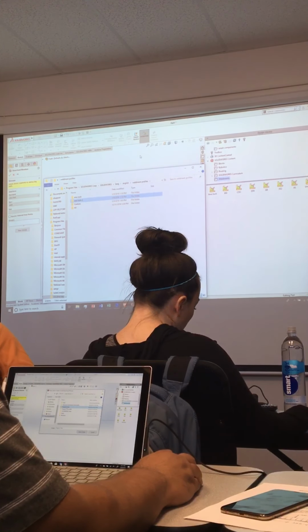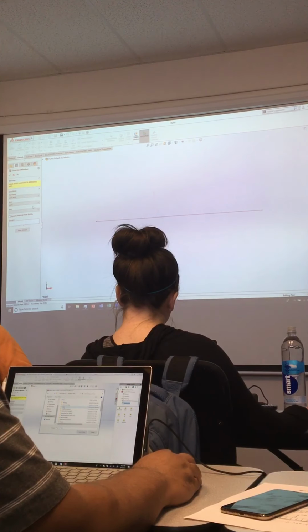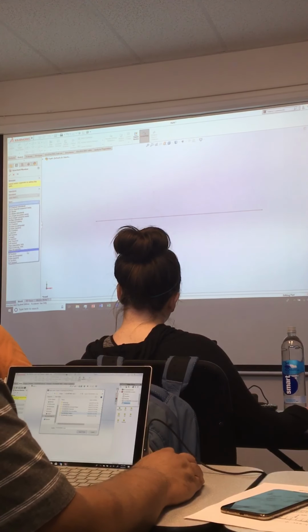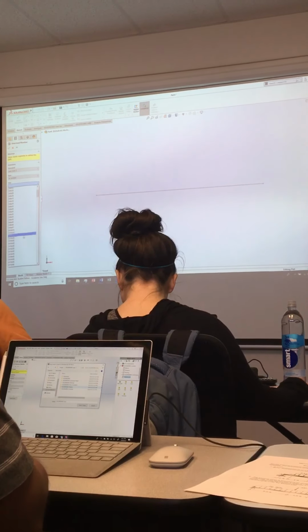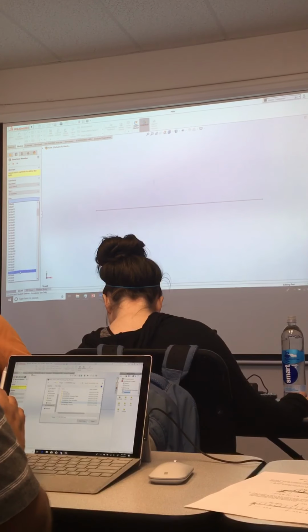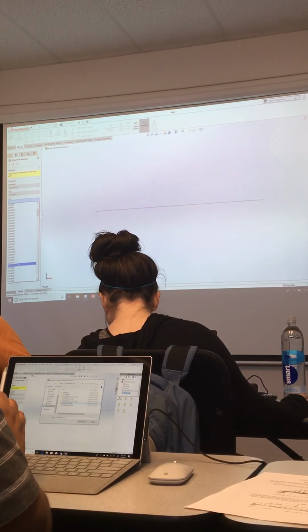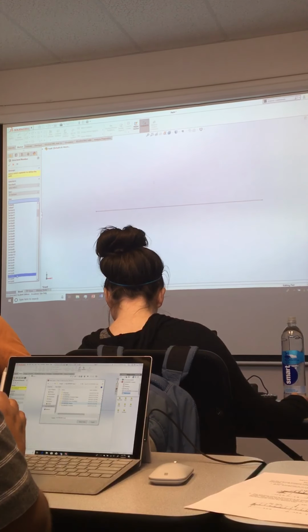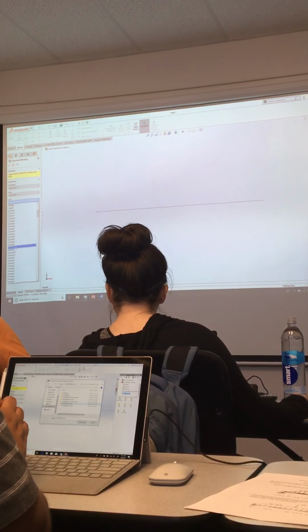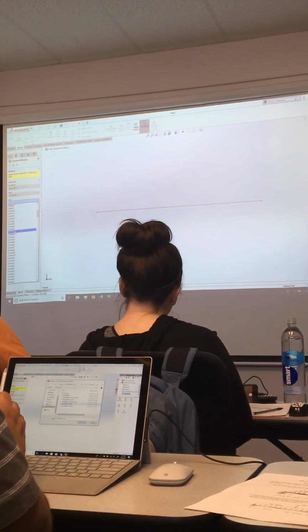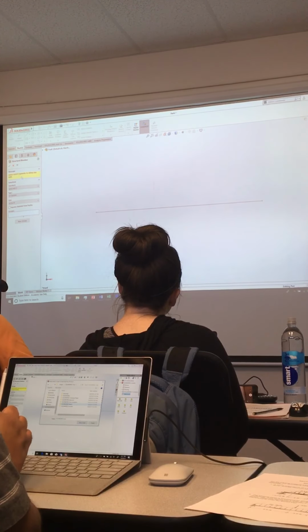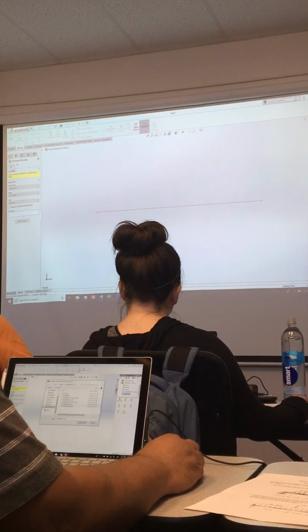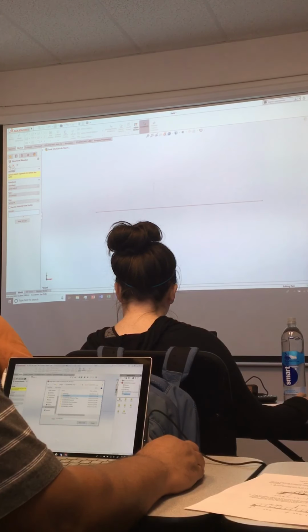So what I want to do is get back here and pick my ANSI Inch 2. I'm gonna do the weldment section, the W section. I can scroll down here to W, and I'm gonna pick a different one just because I'm that kind of guy. Let's pick a 10-inch one here. Why not? I'm gonna pick 10 by 19, and I say okay.